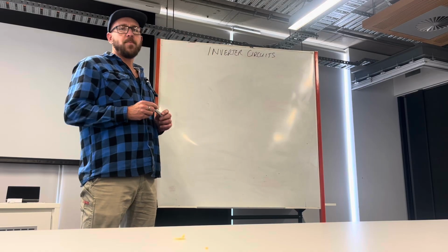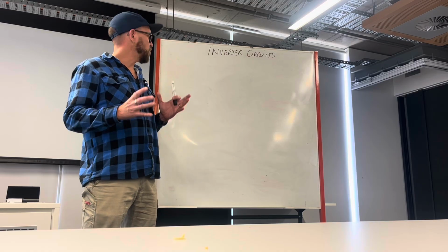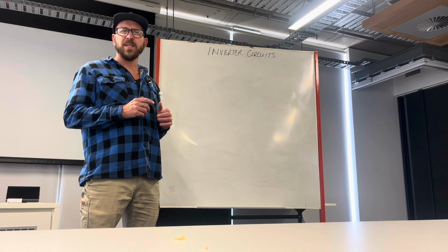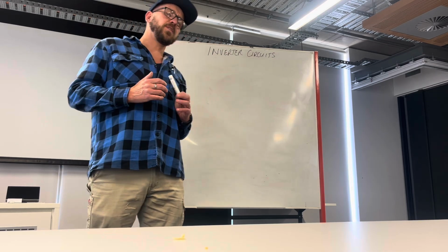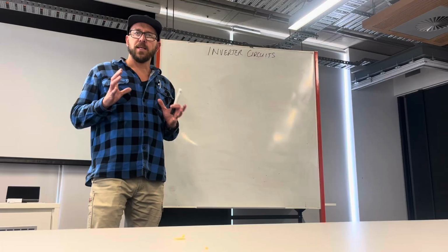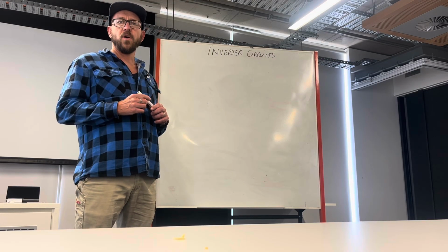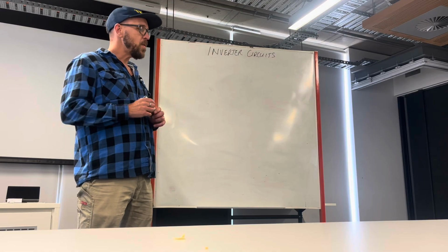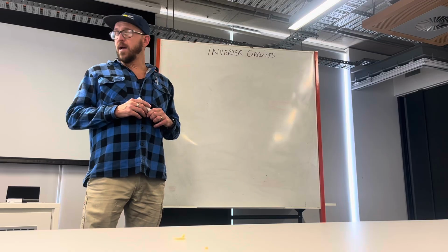Now, some of these smaller splits might just have the one board in the outdoor unit, whereas some of the bigger ducted units could have 3, 4, multiple boards, and it's important to be able to know what the different components are and some expected voltages. That's going to help us fault find and troubleshoot the system, make sure that we're only replacing components that have failed, and give us some confidence in fault finding, making sure we got the right outcome for our customer and we can be confident in testing the system.